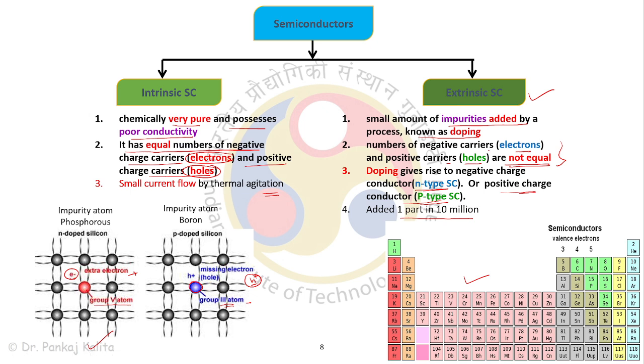So there is always an excess of electrons or holes, depending on whether we are talking about n-type or p-type. In n-type, excess electrons are there, and in p-type, excess holes are there. In the earlier lecture, for n-doped silicon, we doped phosphorus, so we have this excess of electrons. In p-type, we have injected a group 3 atom, maybe boron, which has one vacancy or hole, making it a p-type semiconductor.